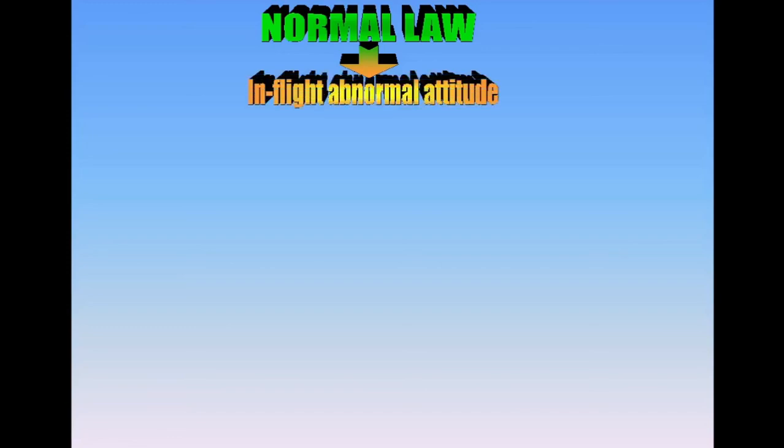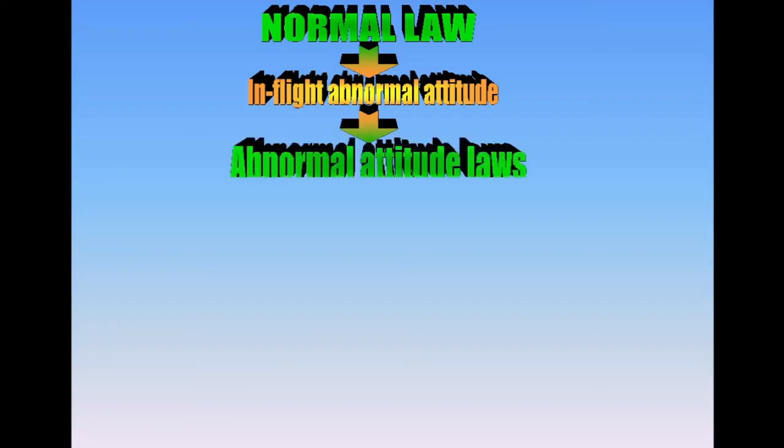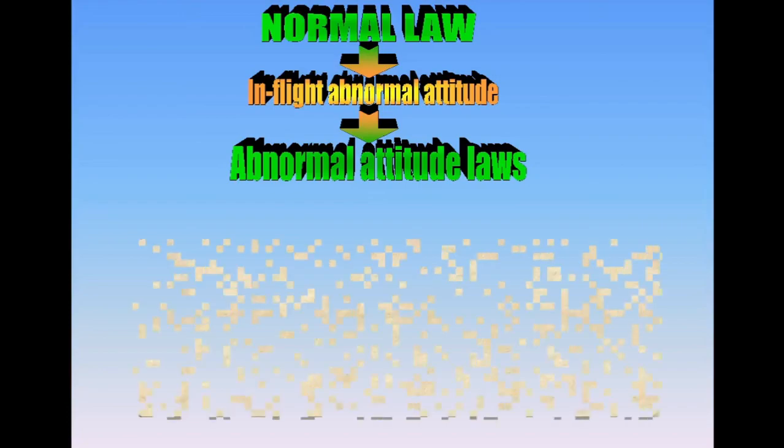You have seen all the different laws and protections. What happens, though, when external forces cause the aircraft to leave the protected envelope? Severe turbulence or a thunderstorm? If the limits of normal laws are exceeded, abnormal attitude law becomes active. This is a safety feature to ensure that the flight control computers will never prevent the pilots recovering from an abnormal in-flight attitude. The flight control laws operate in alternate law without protections and stabilities. Load factor protection is maintained.